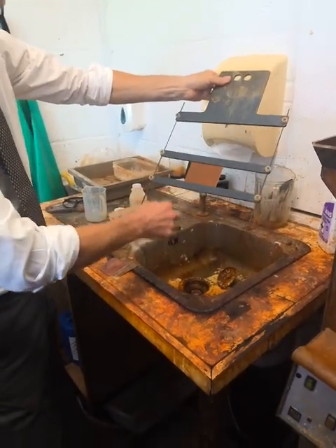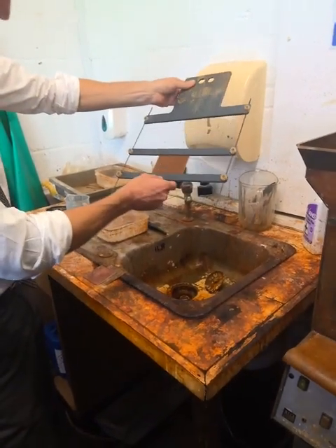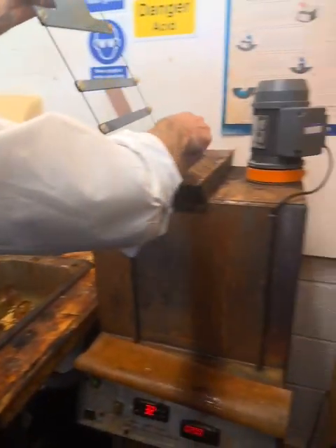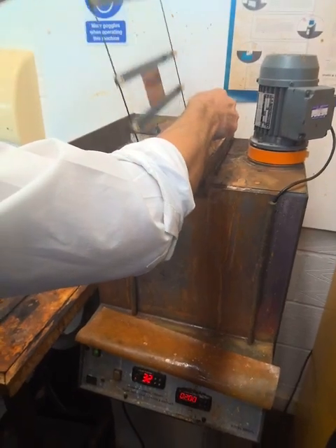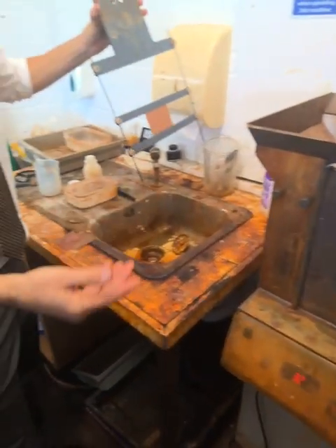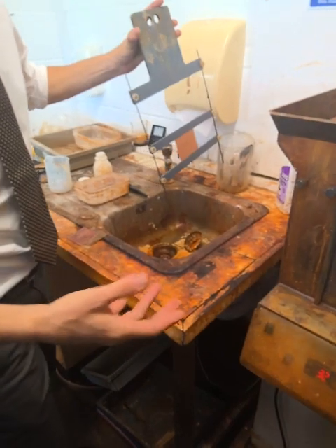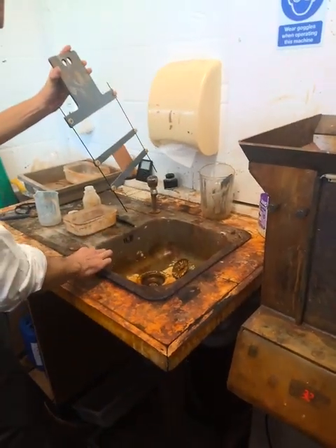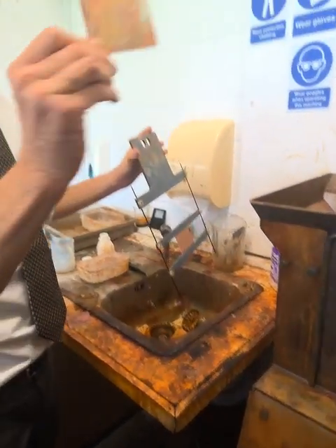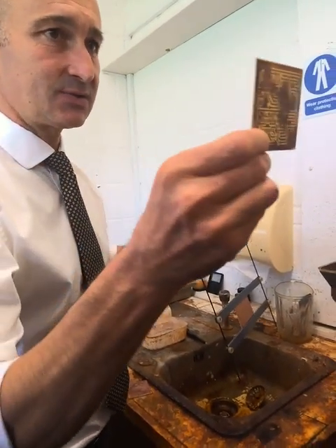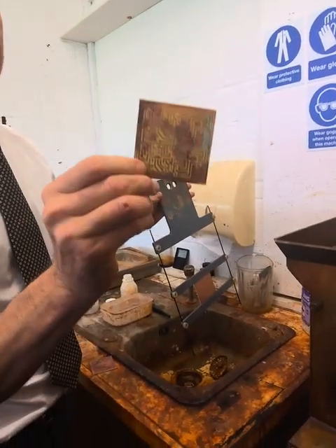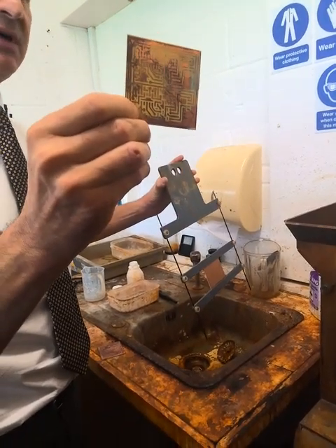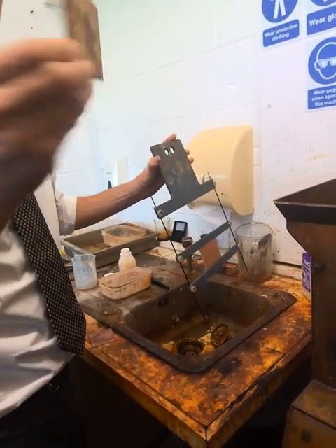So now we've rinsed off the ferric chloride, this is all wet. We have a look at it and we assess it over the sink, and we think, is that good enough? Maybe it needs some more time. We might then want to put it back in here and put it on for another 30 seconds, maybe another minute, maybe another 2 minutes. But generally, you might need another 30 seconds. Are you clear so far? What do we end up with? We end up with something, hopefully better, something like this, where you can see the tracks, and behind the tracks you can see that greeny sort of look, which is a glass fibre, the same colour as the back. Are you all with me?